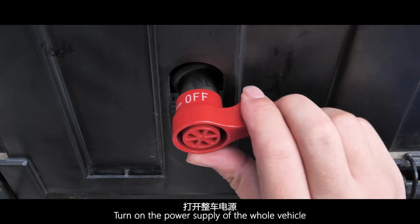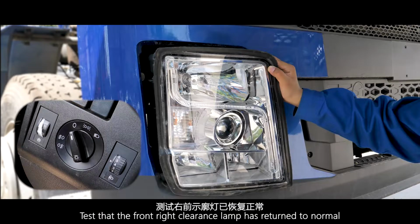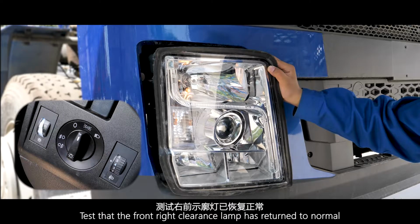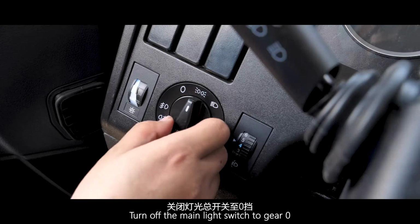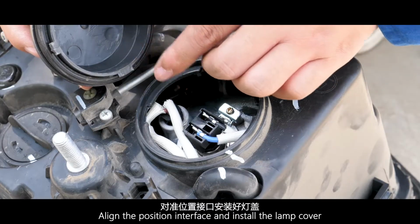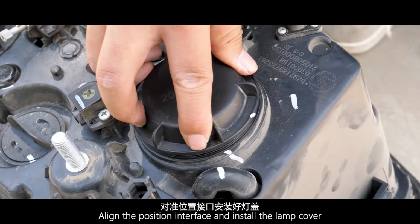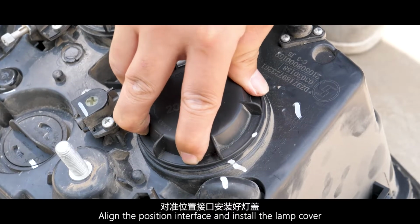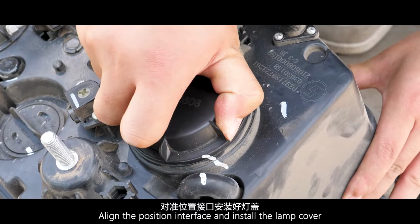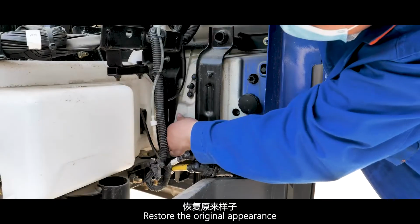Turn on the power supply of the whole vehicle. Test that the front right clearance lamp has returned to normal. Turn off the main light switch to gear 0. Align the position interface and install the lamp cover. Restore the original appearance.